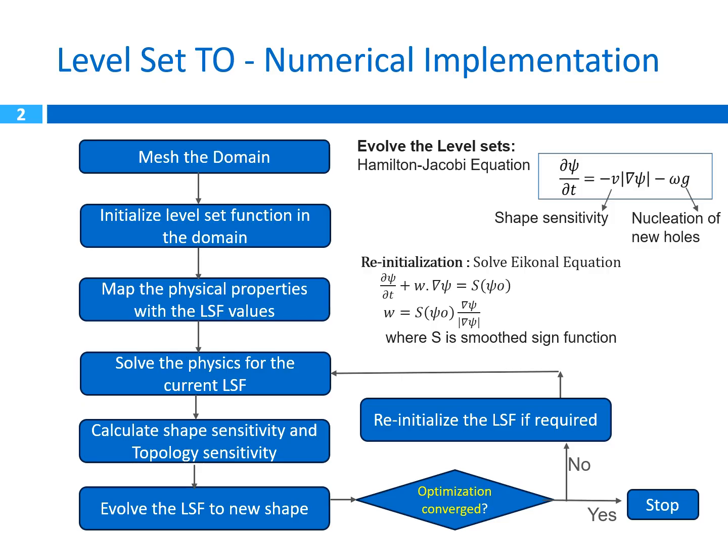During this level set topology optimization, we also need to reinitialize the level set. Reinitialization means bringing back the gradient of the level set function to 1 again. Initially the gradient will be 1, but as you evolve it, the gradient will fall down from the value of 1. It will become slant or steep. So at some frequent intervals you need to reinitialize, you need to bring back the gradient to 1 in order to crisply capture the boundaries of the shape.